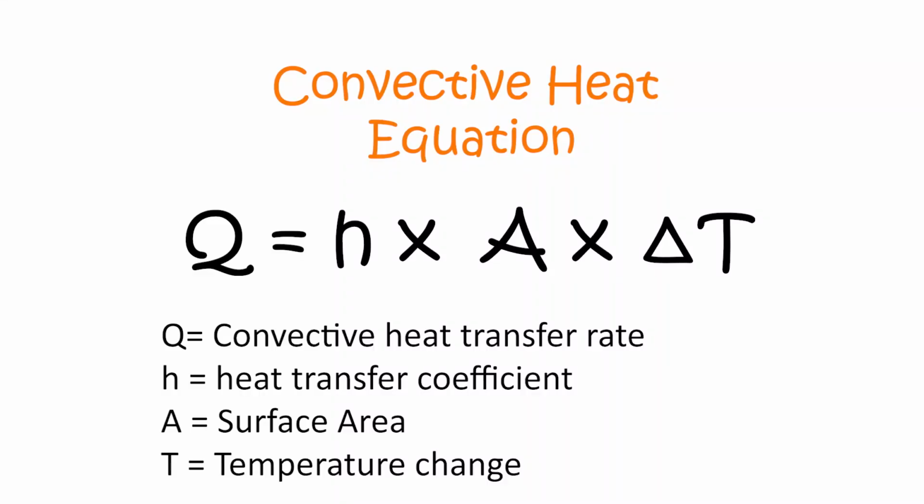The second one would be to use heat sinks, or if you already have heat sinks, you could expand the area. Now, in order to explain this heat sink concept, you can use this formula called Q equals h A ΔT, where Q is the heat transfer rate for convection, h equals the heat transfer coefficient, A equals surface area, and ΔT equals change in temperature.